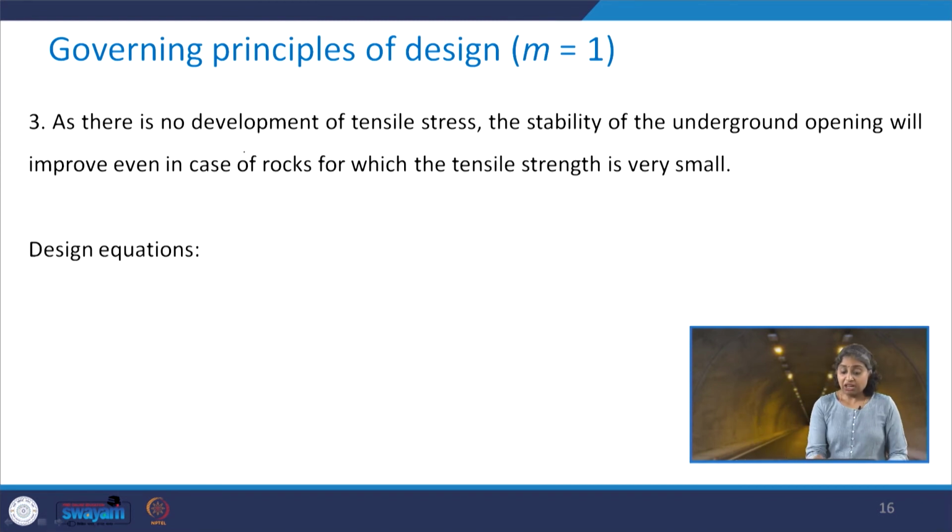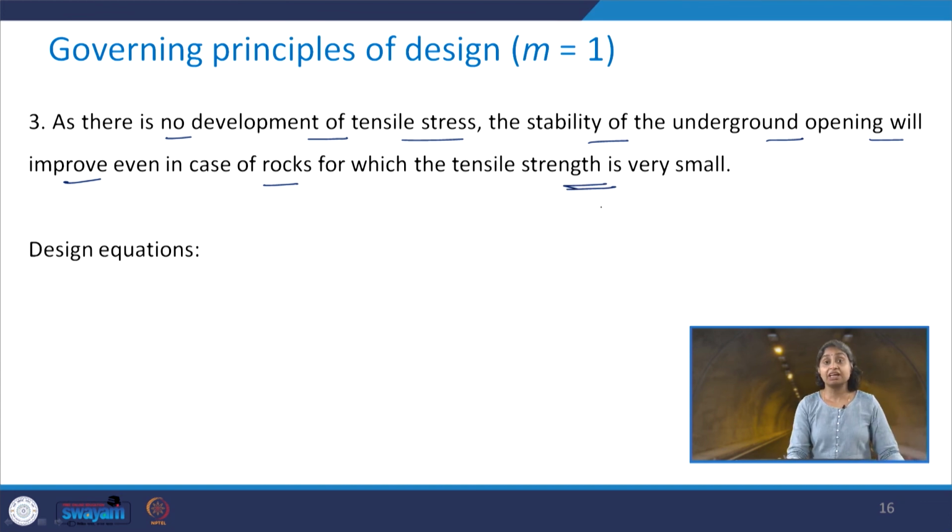Now, because there is no development of tensile stresses, the stability of the underground opening will improve even in case of rocks for which the tensile strength is very small. As I mentioned, you really do not need to bother about the tensile strength of the material.